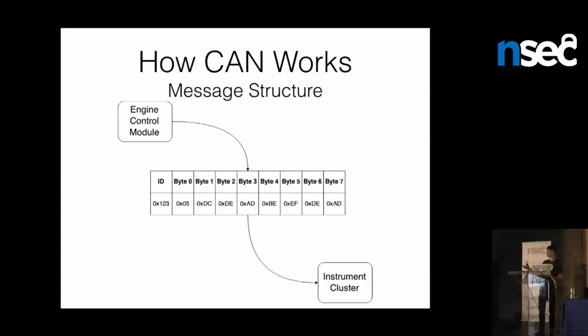And in this case, I said, okay, we'll send this ID 123, and we packed the first 2 bytes with some useful stuff, and the rest is DEADBEEF for fun. And the whole idea here is that beforehand, whenever you actually write the code that goes in these controllers, you have to agree on what byte means what. And you have a database file, essentially, that says what means what. And you would kind of assign some bytes to values.